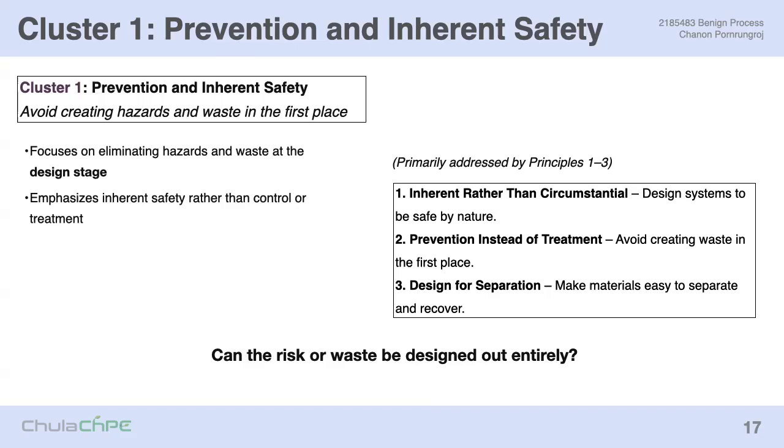The third one is very important for chemical engineers because of most processes, let's say process A and B, A has a very high yield, but that high yield or high selectivity product comes with a lot of solvent in the process. So you have to spend a lot more energy to remove those solvents to get the final product. Versus the second process, maybe you have less yield and less selectivity, but there's no separation needed.